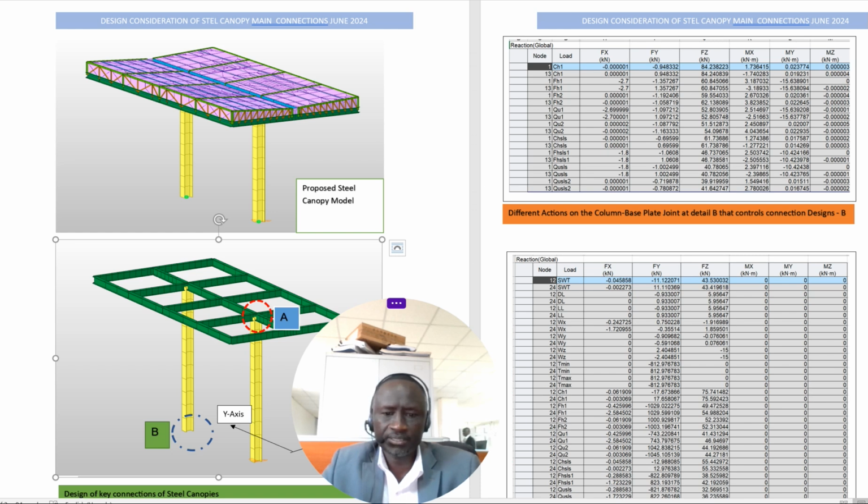Even the geotechnical capacity, the bearing capacity information will be different. So you need to be careful in dealing with parameters regarding soils. Soils in the north, soils in the northeast, soils in the west, here in central and south, they're completely different. And the depth to sound bearing strata also varies. So your foundation will be site specific, based on parameters you determine from there. Yeah, that is very good.